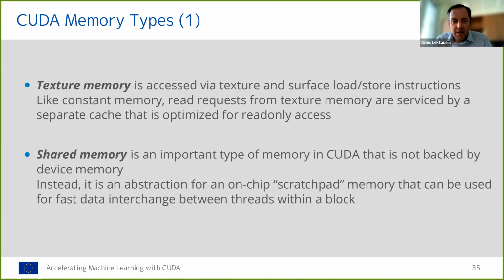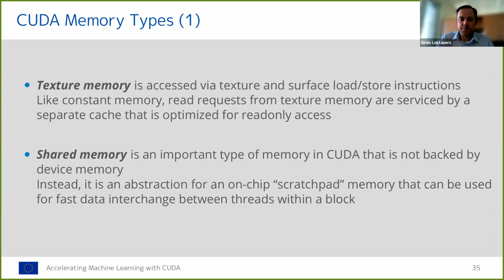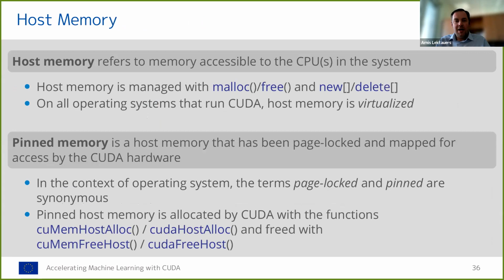Shared memory, I have mentioned previously, is built into the GPU chip. In each streaming multiprocessor, there is shared memory available. Usually it is no more than 64 kilobytes, but in newer Ampere cards, it is already at least 96 kilobytes. And host memory refers to the CPU side.